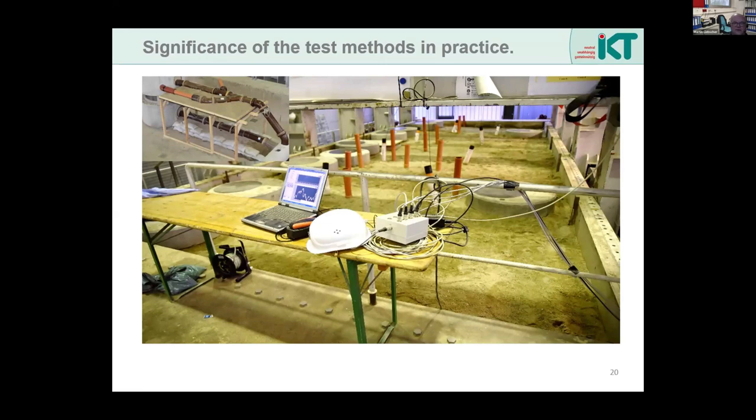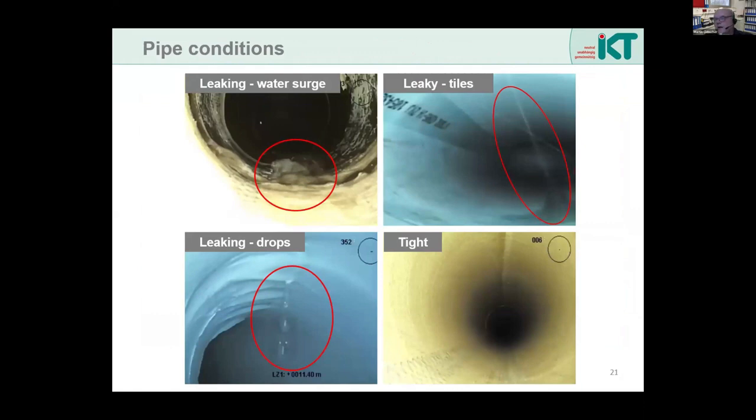And we have also the possibility to change the groundwater level. So we could have a look when water comes in. This was very important because tests are very difficult, as we have seen, and so we could rise the groundwater level, and then we have different typical damages. We have big leakages with really flowing in water.